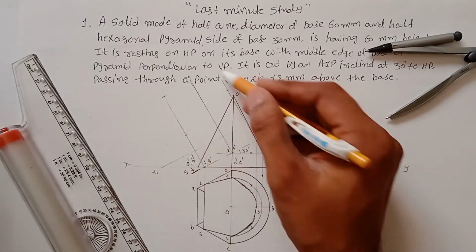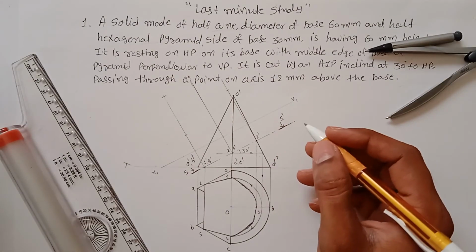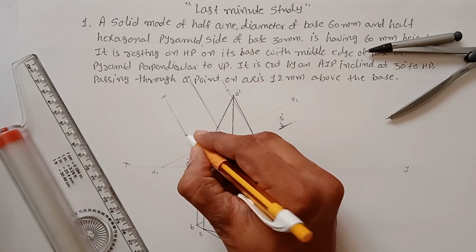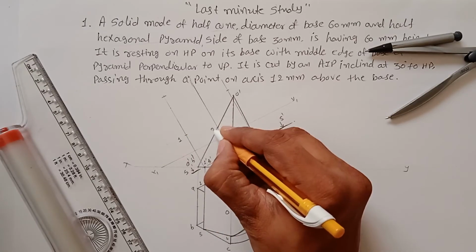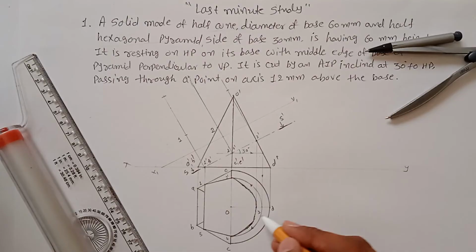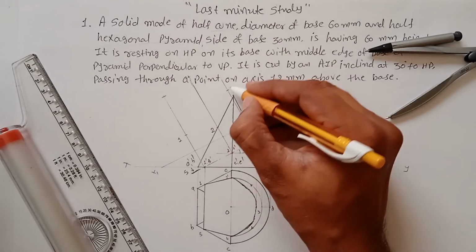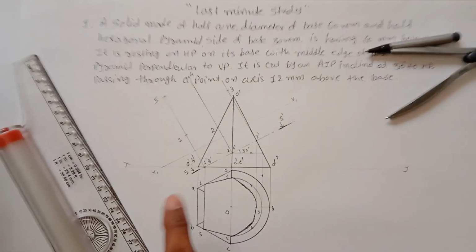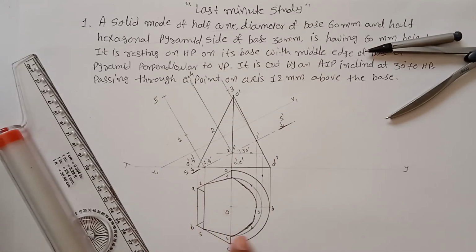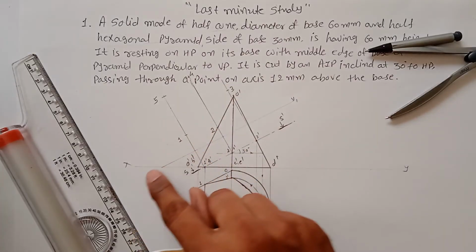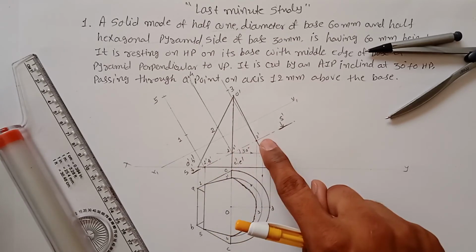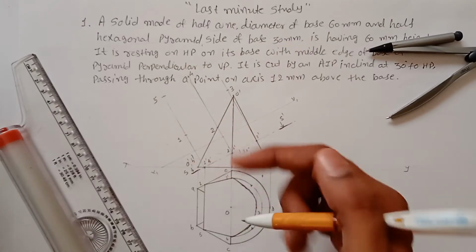Now you have got all your points. Give names to them for better understanding. So this point is the first point, this is 2, this point is the third point, this point is 4 and 5th. Remember, you have to measure 1, 2, 3, 4 from the XY line, and you have to give dimensions on this X1 Y1 line. Don't make the mistake of measuring from 1 dash, 2 dash and 3 dash. Okay, that is wrong.